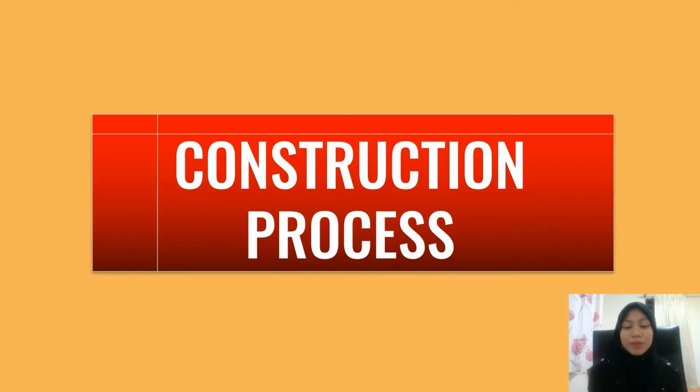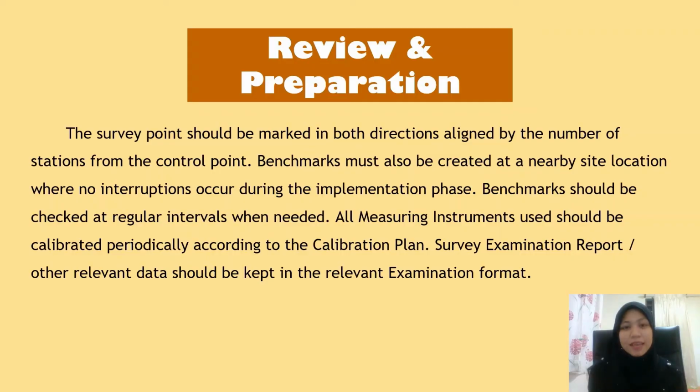Next, construction process. First, we have to do review and preparation. The survey point should be marked in both directions aligned by the number of stations from the control point. Benchmarks must also be created at a near site location where no interruptions occur during the implementation phase. Benchmarks should be checked at regular intervals when needed.